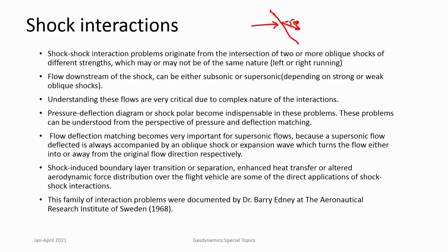This kind of shock turns the flow from the upstream direction towards the right, and this is known as a right running shock. On the other hand, if you had a shock of this nature and this is the incoming flow, it turns the flow towards the left. So, this is known as a left running shock.